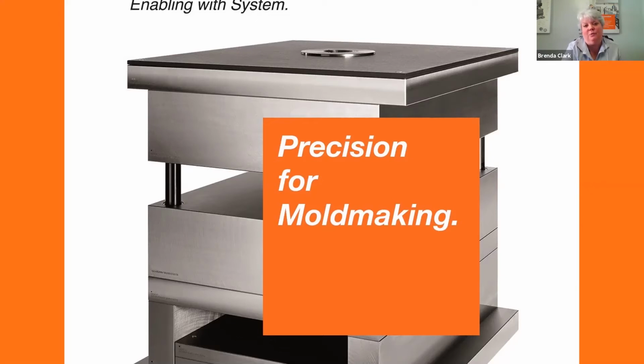We have numerous components that were once installed into the mold that were standard steel, and customers were constantly having to maintain them and replace parts over the years. Once we DLC coated, for instance, a 2-stage ejection unit, they saw a 3-to-1 increase in the longevity of the part. So yes, it is expensive. However, it pays for itself in the long run.